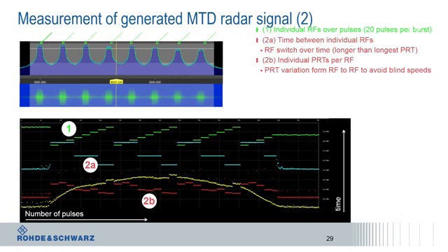Look at the dotted lines. For the second and for the third RF, the pulse repetition time or pulse repetition interval is different from the first RF. This you can see as it has changed its position. Look into the white circles. This longer PRI can be used to detect objects in longer ranges. This longer PRI is the time the radar needs to switch from one RF to another RF.